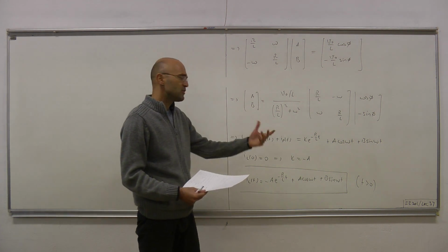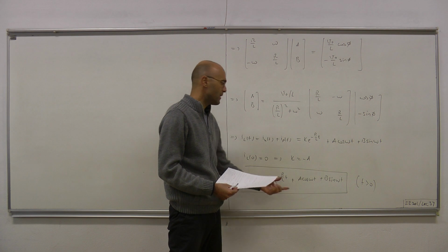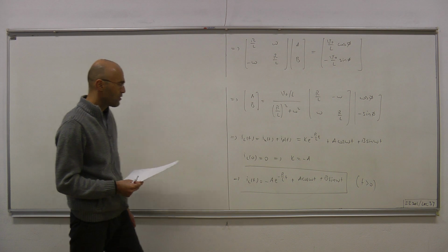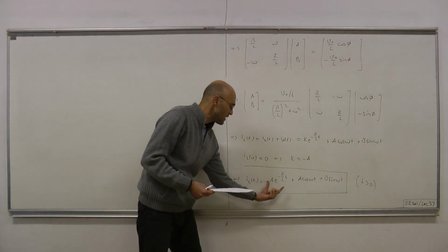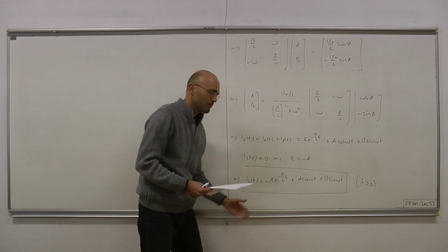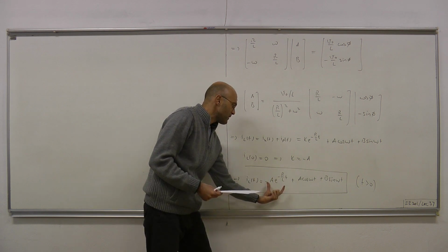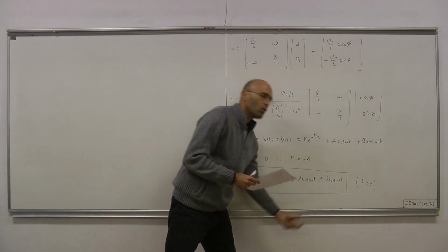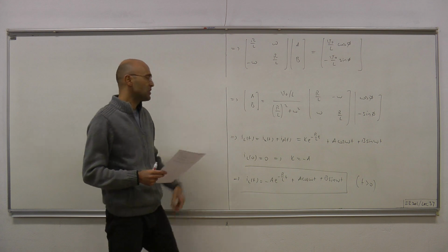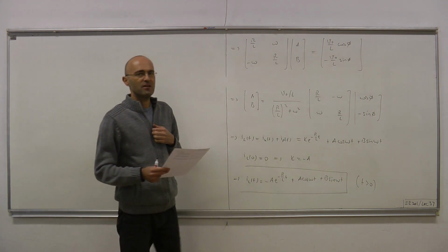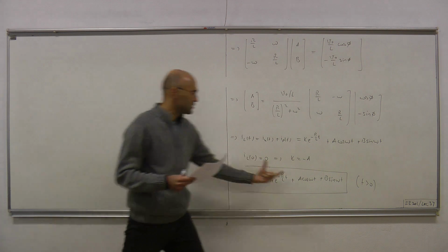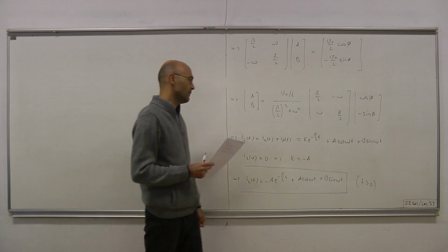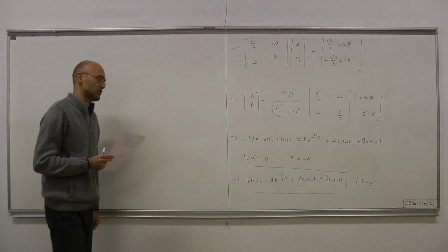In the limit, that is for t quite large, we can just ignore this part, and what remains is only the sustaining oscillation, the sinusoidal part. For that reason, the exponential part is sometimes called the transient part, because it has some contribution only in the beginning, and the remaining part is called the steady state part. Of course, this is a different steady state than the DC steady state we have seen. This type is called the AC steady state or sinusoidal steady state, which we will study in detail in 202, next semester.